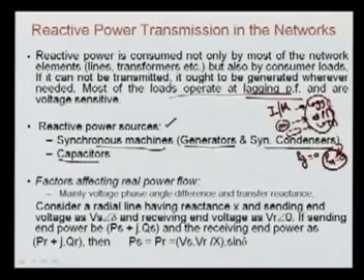Another reactive power source is the capacitor, and again putting a capacitor in a high voltage network is very difficult, in EHV as well as UHV transmission systems. So we try to put these reactive powers through the capacitors in the distribution network. The capacitors are normally installed near the load centers so that the requirement of reactive power of the loads is met locally, so that we should not flow the reactive power over the transmission line.